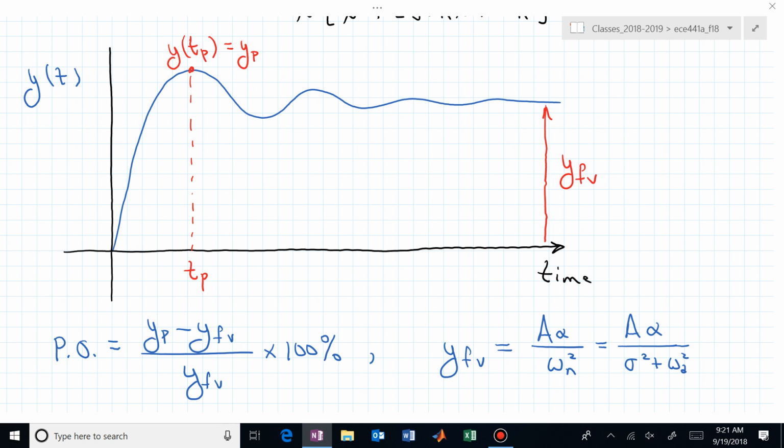And when I say natural frequency, what do you now see or think? The distance that pole pair is from the origin. That's your natural frequency. How far away from the origin is that pole? If I say sigma and omega sub d, that tells you the rectangular way to get to that same pole.